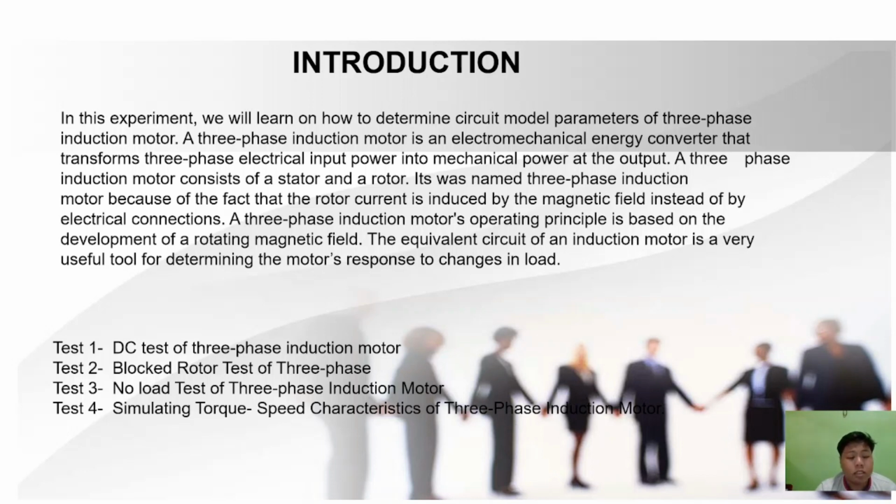Okay, test 1, we can do a DC test of the three-phase induction motor. Test 2, blocked rotor test of the three-phase induction motor. Test 3, no load test of the three-phase induction motor. And the last one, test 4, simulation of the torque speed characteristic of the three-phase induction motor.